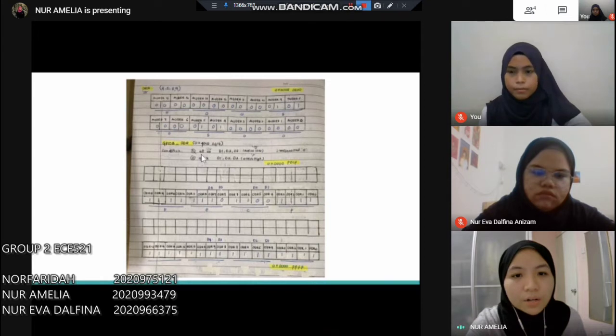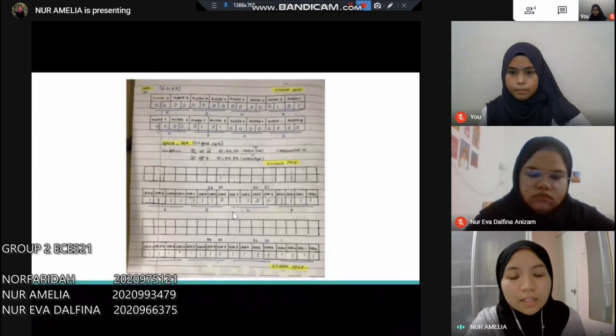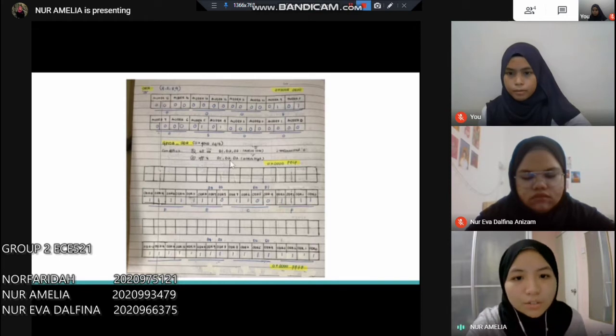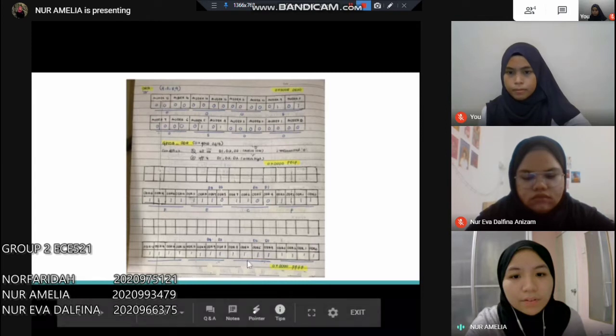The first one, we need to turn on LED D1, D2 and D3 by putting logic low in this program. After we put the value, the value would be 0x0000FECF. For the next condition, we need to turn off D1, D2 and D3, which are active high. So we put all logic high, which produces the value 0x0000FFFF.